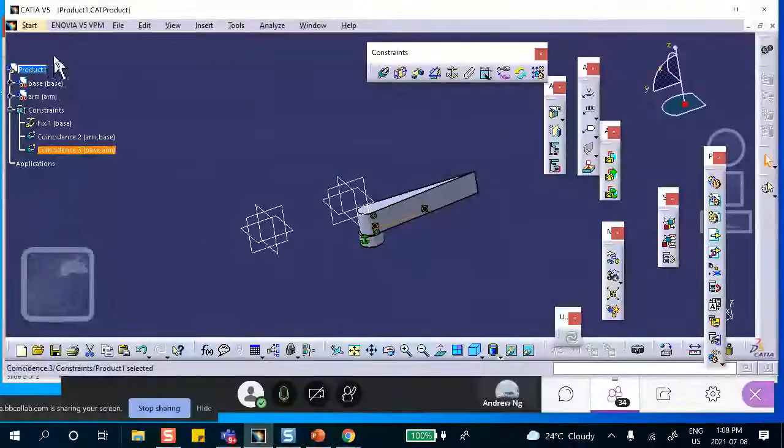All right, good. So these are the assembly constraints, and axis to axis, plane to plane, that becomes a revolute joint. Okay, remember the first problem that we did was not axis, it was edge to edge, plane to plane. That became a prismatic joint. The thing traveled along that track, okay? All right, so let's save everything first of all.